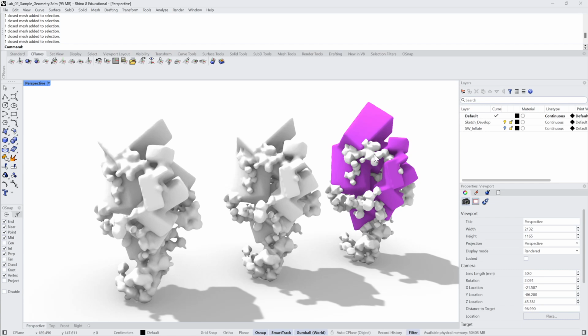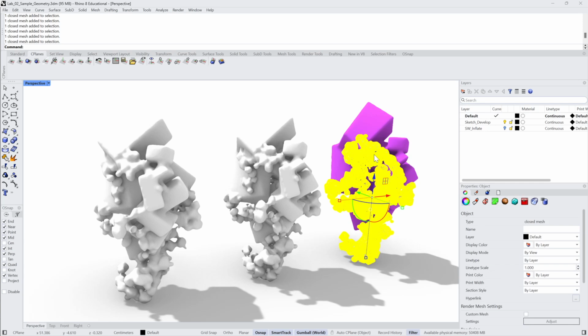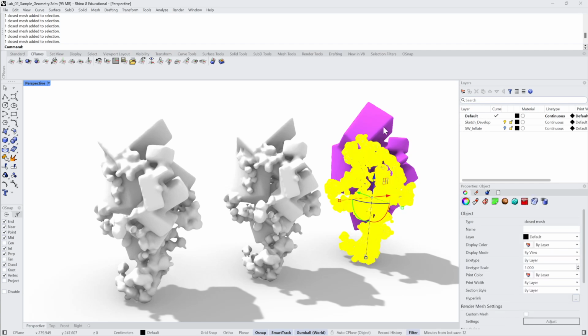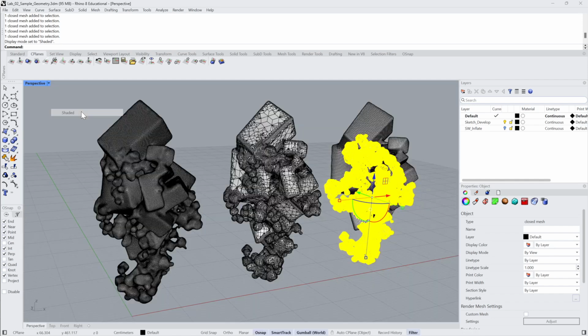Then I used a little Grasshopper to scatter some objects onto the original mesh. I then moved this scattered mesh down and shrink wrapped that, and then I shrink wrapped everything together, and then I used the quad remesh tool to have nice topology.